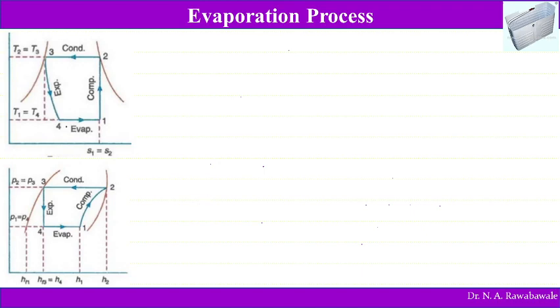Now after that, the refrigerant enters into the fourth device, known as the evaporator. So here, 4 to 1, when refrigerant, which is in the form of vapor at low temperature, low pressure, enters into this evaporator and gets evaporated. That process is shown on the pH diagram here. Now here the refrigerant absorbs heat energy Q in, which we call the refrigerating effect, RE.